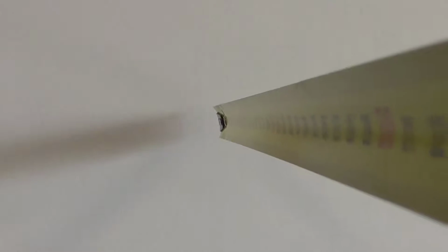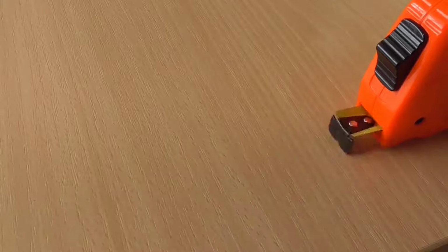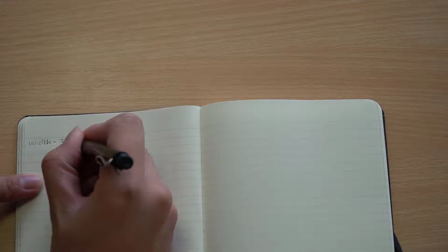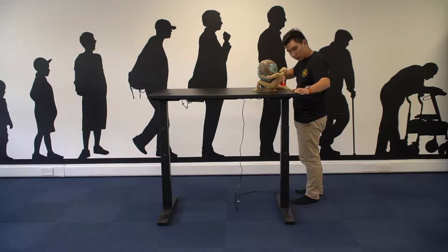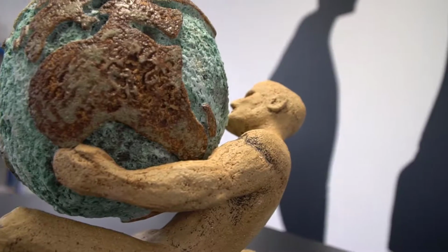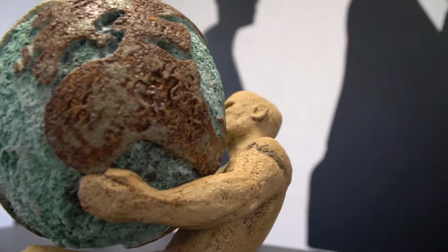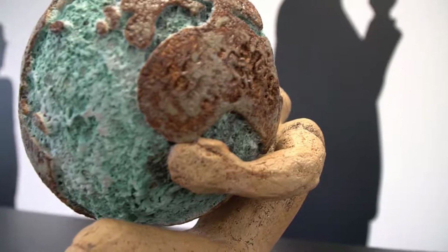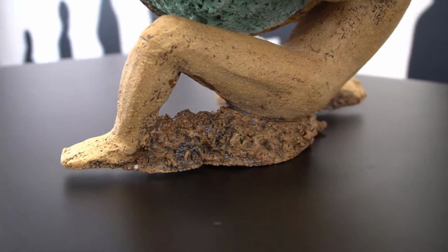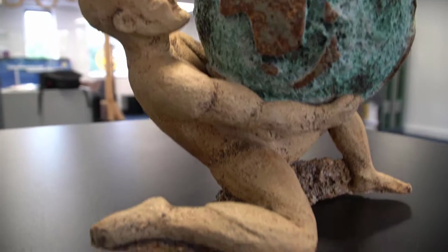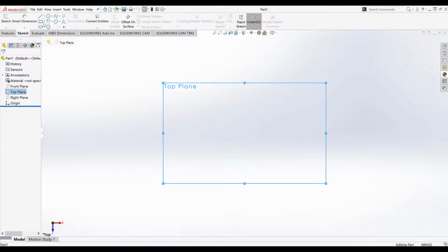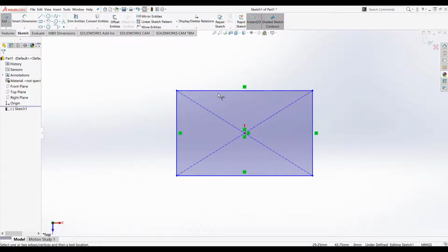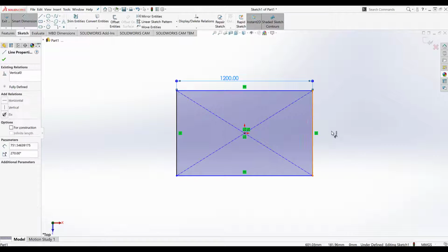Looking at the option of physically measuring the environment that you're trying to capture, it involves using physical tape measures, vernier calipers, or any other tools to measure and note down all the dimensions of it to recreate it digitally. So it's great for simple forms like tables, shelves, and other simple geometric shapes. But when looking at more complex forms like sculptures or anything quite fine in detail, you wouldn't choose to use this process as the accuracy isn't great and the time you have to invest is quite high, because after you've measured it all, you have to use CAD software to recreate it again.